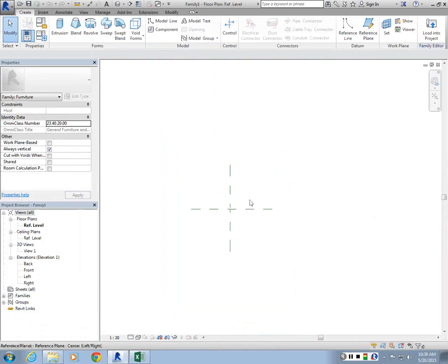Now this will bring a little bit different environment than we've been working with so far in Revit. In a family, if it's a hosted object, let's say like a door or window, you would also have a template wall inside the family drawn, and you will actually model your custom door or window inside of that wall, so that when you use it in project, the relationship to the wall that you have modeled in would be used.